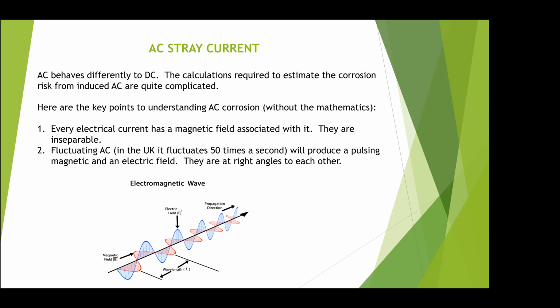induced. And there's nothing you can do about this, because these overhead power lines carry very high voltages and currents, and they generate big fields, and they're changing 50 times a second. And there's nothing, absolutely nothing you can do about it. And if it happens to be feeding a factory, particularly one, say, with welding or with equipment that changes the electrical phase, you'll find that the third harmonics all add up. So what starts off as a relatively small voltage gets bigger because the third harmonics are in sequence and they add up to each other. So that is what causes the problem.